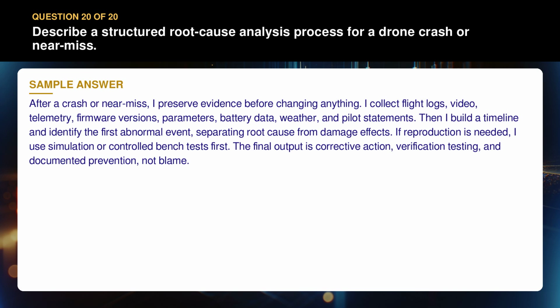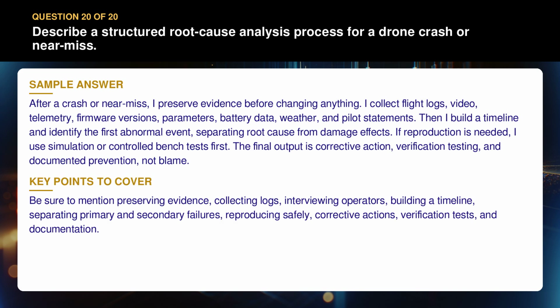If reproduction is needed, I use simulation or controlled bench tests first. The final output is corrective action, verification testing, and documented prevention. Be sure to mention preserving evidence, collecting logs, interviewing operators, building a timeline, separating primary and secondary failures, reproducing safely, corrective actions, verification tests, and documentation.